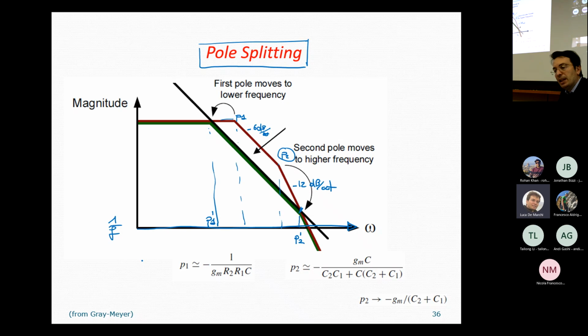This is also what can be called a null. Okay, the gain, the DC gain. At high frequency, we indeed have the effects of the two poles and the zero. Please remember that the dominant pole is induced by the Miller effect, which means that its value is given by the compensation capacitance CC times the gain of the second stage.